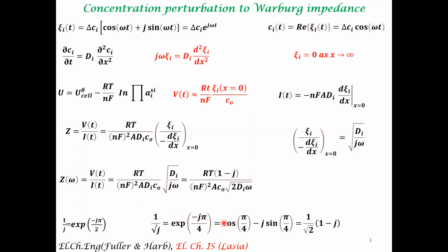All right. So what is most important are these two terms. So that's what we are going to focus on. So typically, this form of impedance called the Warburg impedance is just due to limitations in mass transport. So this is the relevant circuit, the Randles circuit gets modified by a Warburg impedance, which is in parallel to the Faradaic resistance.